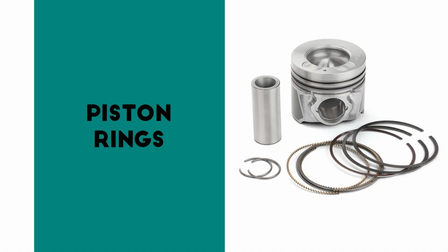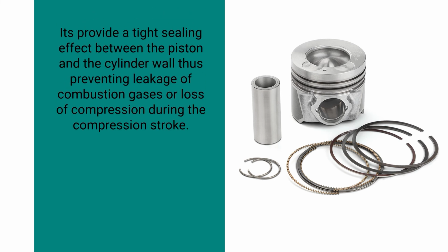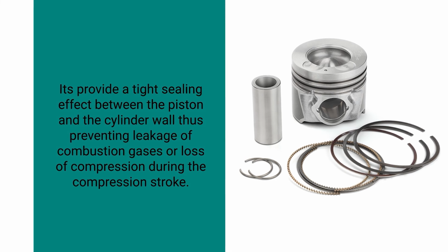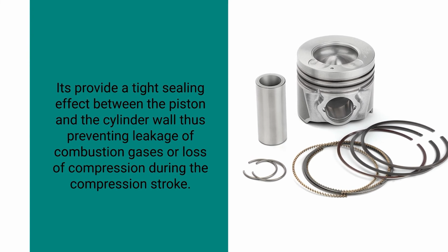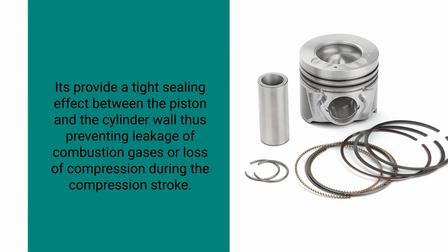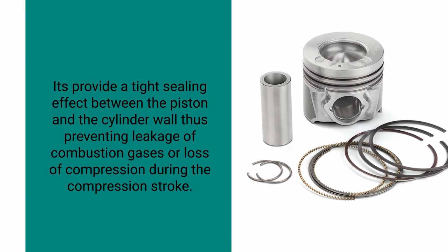Another important part is the piston rings. Piston rings are fitted in the grooves around the piston. They provide a tight sealing effect between the piston and the cylinder wall, and thus prevent the leakage of combustion gases or loss of compression during the compression stroke. So, piston rings, my dear friends, play an important role. If there is wear and tear, gases will leak and there will be less power on the crankshaft.